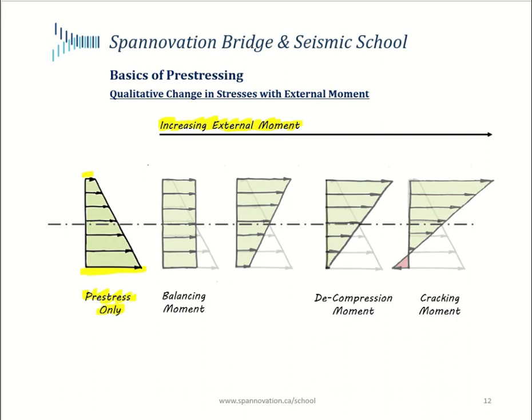Now, let me just quickly switch to a marker mode so I can draw something. The other thing is the stress line of a stress diagram is this, the front line over here, this one. And you'll notice that as the external moments are increased, this line would pivot about the neutral axis. So this is the pivot point.